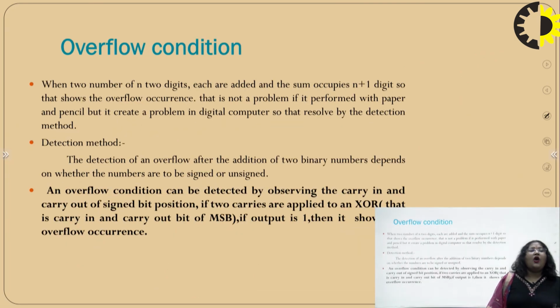Now, this is the overflow condition. The basic rule of the overflow condition is that overflow can be detected by observing the carry out and carry in. If the XOR of carry out and carry in is 1, that shows an overflow occurrence. If it is 0, that means there is no overflow.